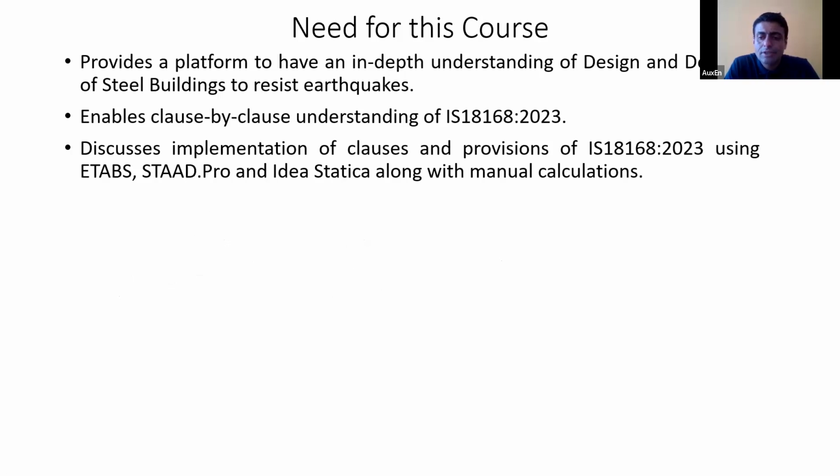Mr. Ayal is asking, but sir, if it's a copy of AISC 341, can't we just use 341 in software? Actually, you can, but while copying, they have made IS 18168 more conservative, meaning they have put in some additional safeties. What the Indian Codal Committee typically does is pick up a clause from the international standard and make it safer when it puts it in the Indian code.